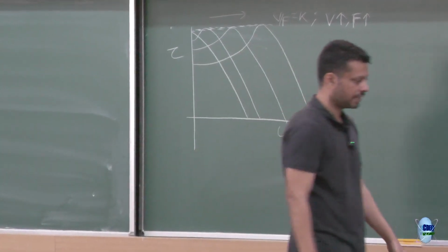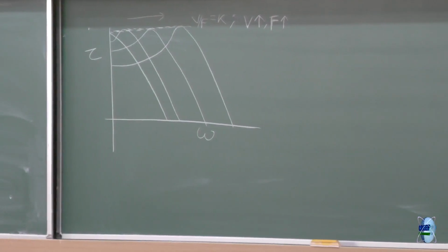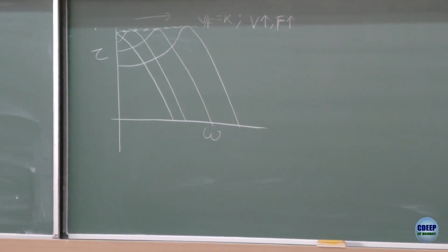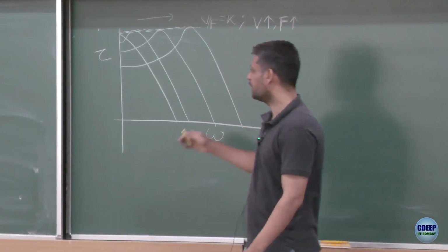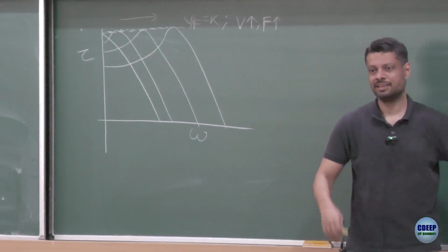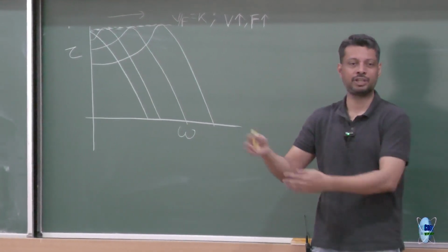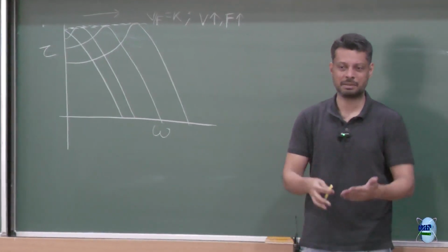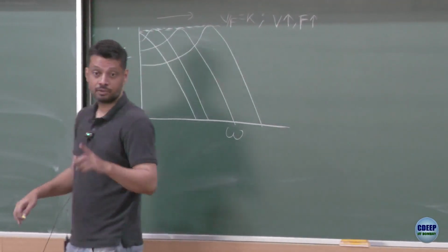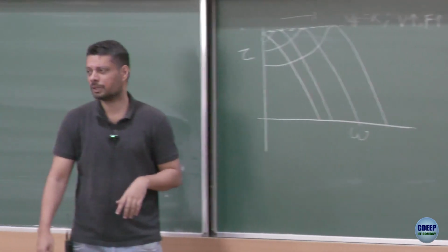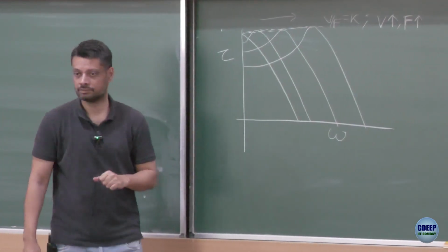And then you have the load characteristics. I asked you to derive it. Either I would have asked you to derive or I would have derived it. Most likely I would have asked you to derive, because that would require you to differentiate this expression, do d tau by d omega, put it equal to 0, and solve. Not in 240, but in 114, sorry.